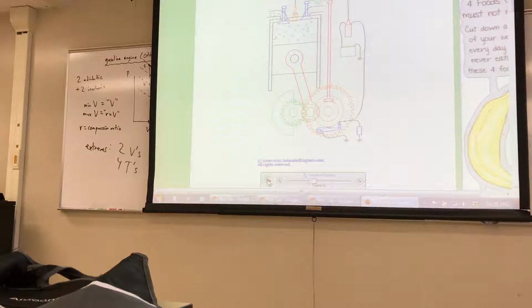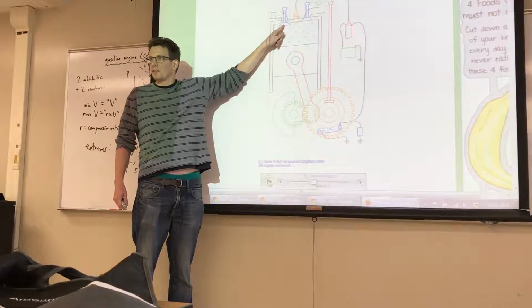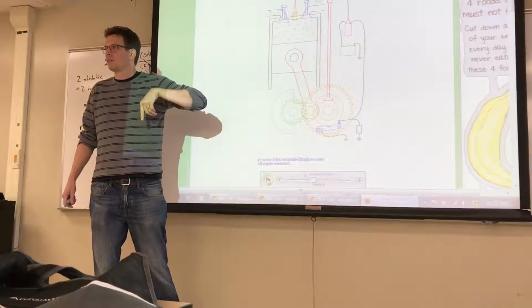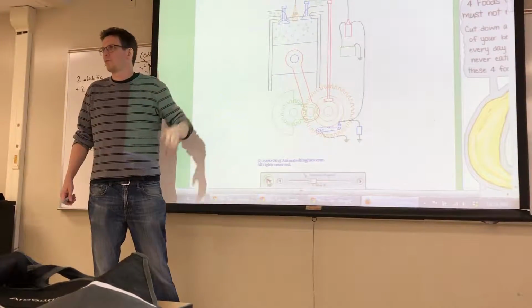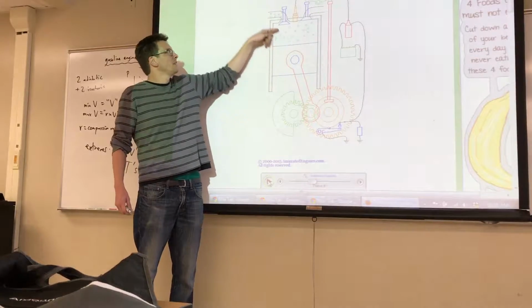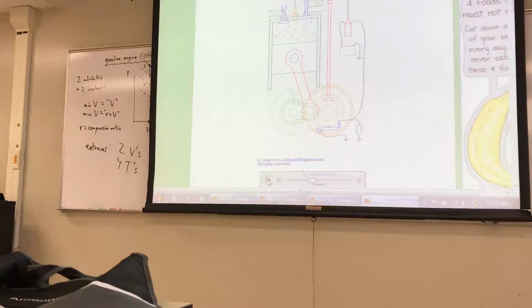Now I want to point out that the intake valve is not tied to anything. I don't have a lever or anything. How did that know to open? Just drawing in a vacuum, right? So if this was empty and this is air pressure, that's just going to push it in. It's just going to open the valve naturally.